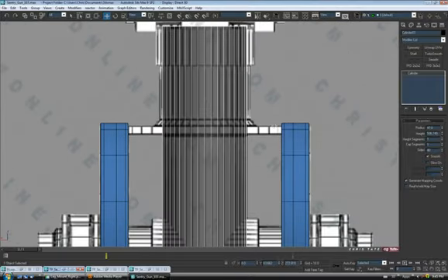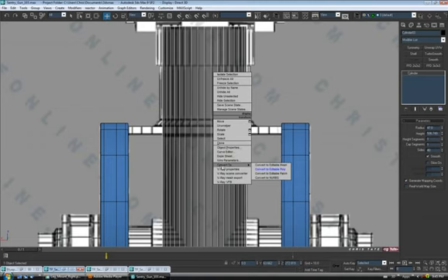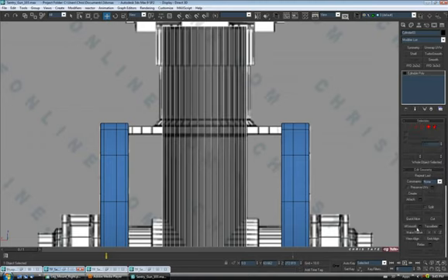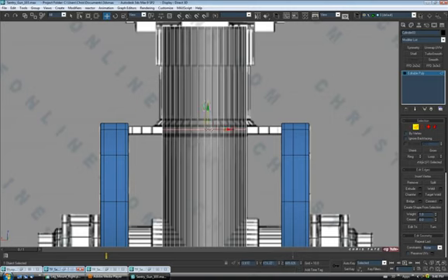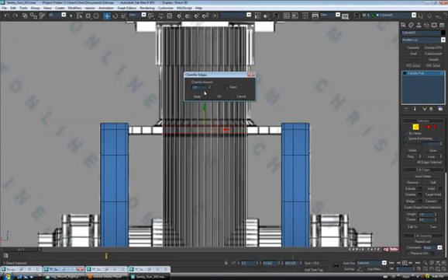And then we'll jump back to the back view and just zoom in here. Alright, so for this piece that sticks out on the sides here, I'm just going to convert this to double poly first, and then let's just use quick slice here. I'm just going to cut an edge in here. Alright, so click over here, go across, and just click. And then we'll just grab that loop, and let's chamfer it. Alright, so we'll go up, let's do, I can probably do 4 on that, and we'll just move it down a little bit.